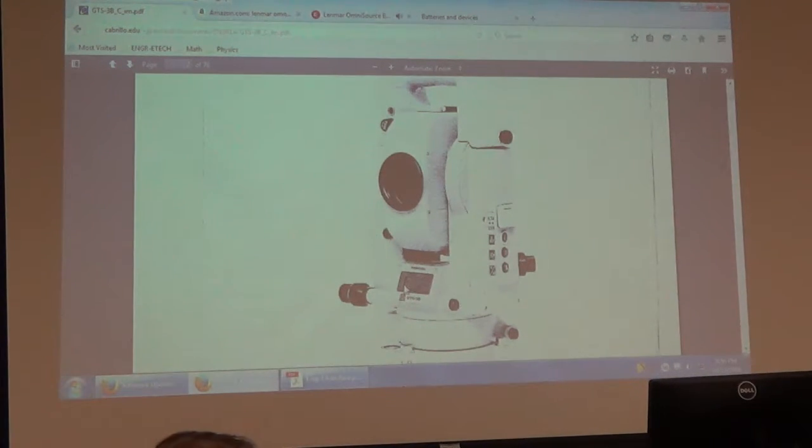Always set it up in the middle, because otherwise you have a lot of movement, a lot of play. So level the thing and get it in the middle of the tripod, because if you keep it loose on the bottom, it can still slide around. Once you tighten it up, then it's kind of set, but you still have the ability to move it around. So try to start in the middle, and you want to be somewhat close.